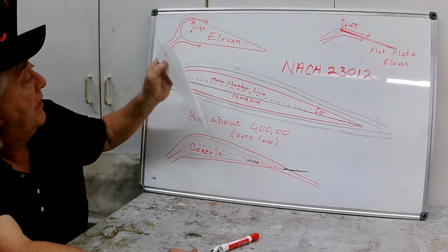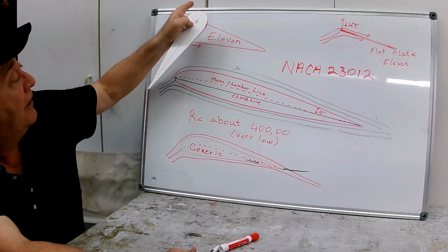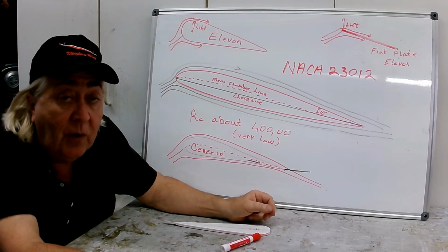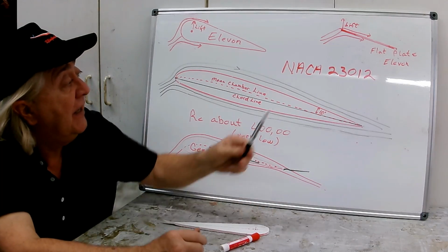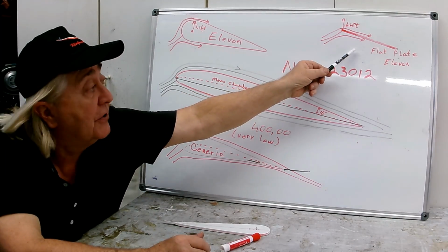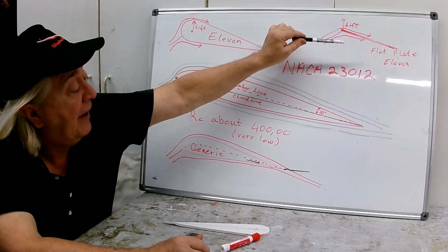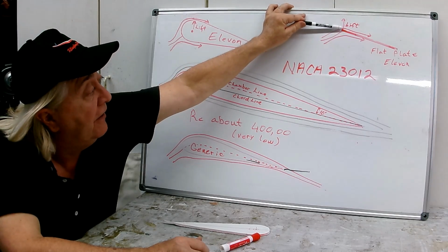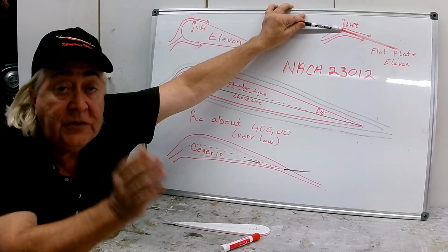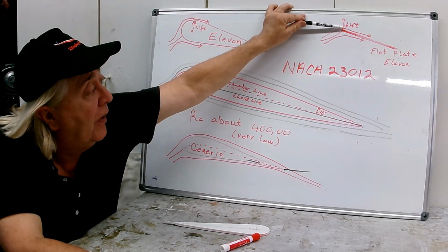So these are great for control surface because they generate quite a bit of lift. If you watch the CFD video and that analysis, you'll see that I end up with a flat plate solution. I'm showing that over here. And if we look at a flat plate without the airfoil in front of it, the lift is generally right here, almost at the very leading edge of that flat plate. It's way, way, way up front.